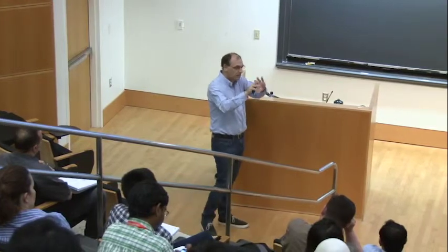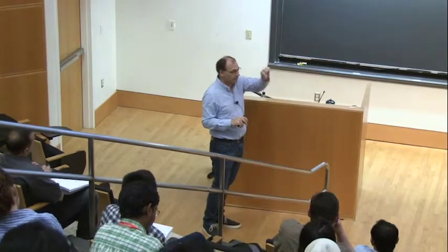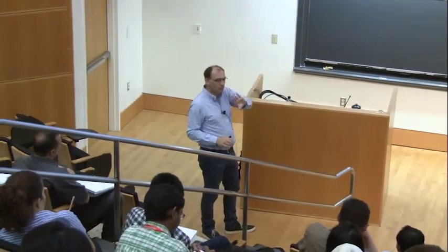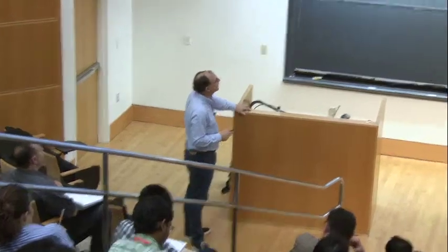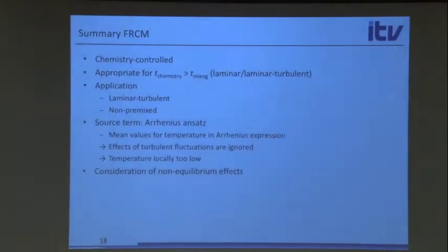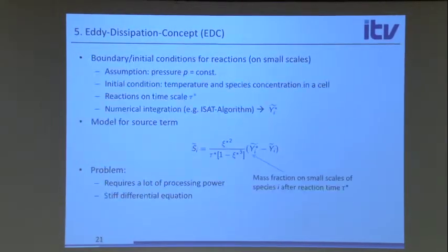So once you tune these, then you say, okay, for this engine, for this operating point, this is not bad, and now I can do parameter variations. Now maybe you inject a little earlier, a little later, or a little more EGR, a little less EGR, then you do a parameter variation just around this point. So that's the tuning. Some of these models have tuning parameters, others don't really have tuning parameters.